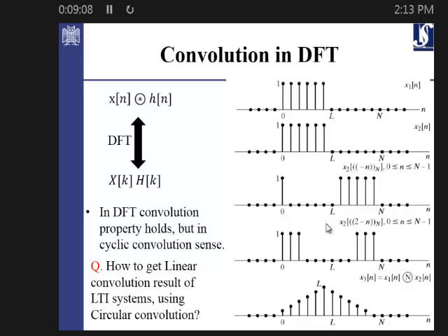So here, if, for example, we have x1 defined as such, and x2 like this, when we mean convolution, well, you already know from the continuous time signals that for the case of the convolution, one of the signal or a filter should be first symmetrically reversed in time, and then you start to multiply by shifting the filter, for example. You shift it and multiply it by the signal. Shift it, multiply it, and then sum up everything and put it for the sample. Here we also do the same thing, but we already know that everything should be done in a window.